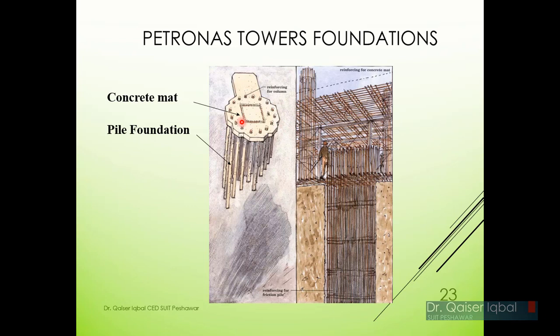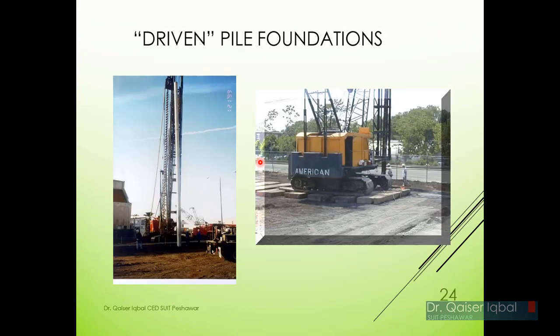Okay, there was other geotechnical challenges in Petronas Tower as well, because the first site at which they were building it, at that site they had the sinkhole issues. Okay, there were carbonate rocks at that location, and you cannot build on carbonate rocks because they can dissolve with time in creating a void. We will discuss them later on, sinkholes, in the same chapter. So this was once again application of geotechnical engineering, which basically made it possible to construct such a large building at a particular location. So if they did not have the geotechnical engineering knowledge, they could not construct at that location.